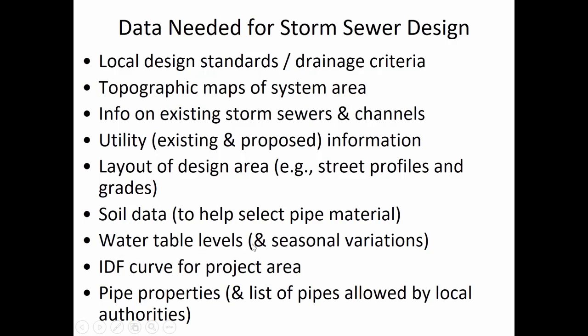We need to know the water table levels, because if the water level is very close to the surface, that could make a buoyant pressure push upward on plastic pipes, and those plastic pipes could potentially come through the surface. I've got some pictures of this. They sometimes have that problem when they're doing maintenance on gasoline tanks at a gas station.